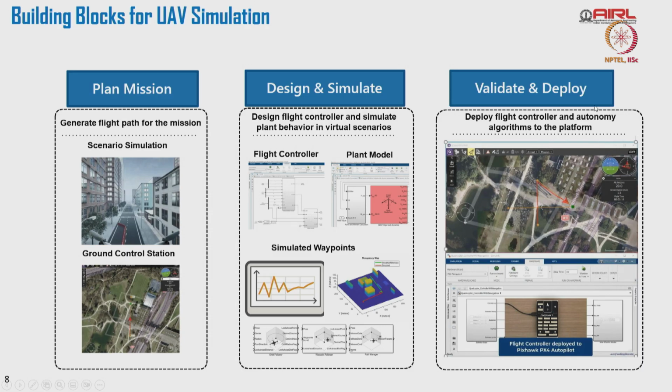And you have to check how your autonomous algorithms are really performing. So hardware in the loop validation you need to do. How your Pixhawk is responding, how your Jetson is processing the data coming from your camera or LiDAR and gets your decision control system, and that decision control system is passed on to your flight controller, basically a trajectory, and how the inner loop, that Pixhawk, follows the trajectory as accurately as possible. This is also important, right?